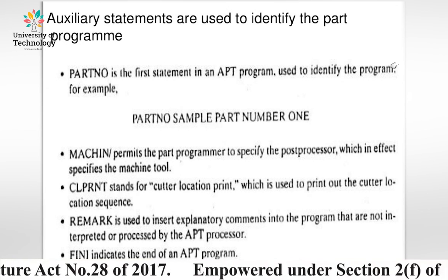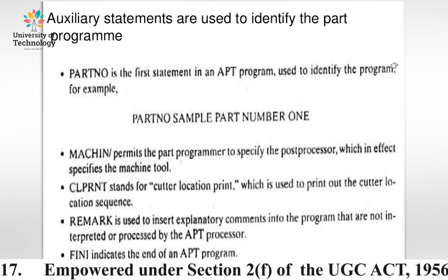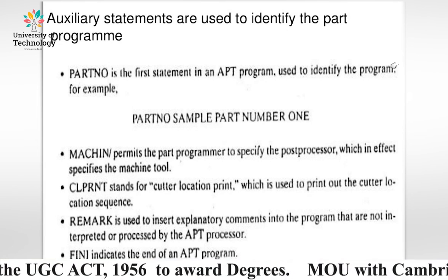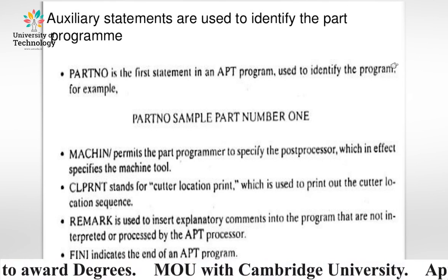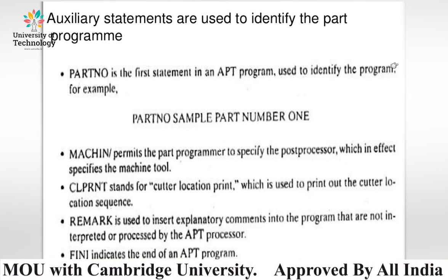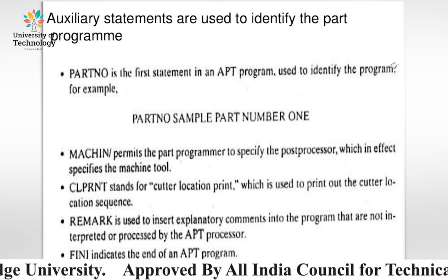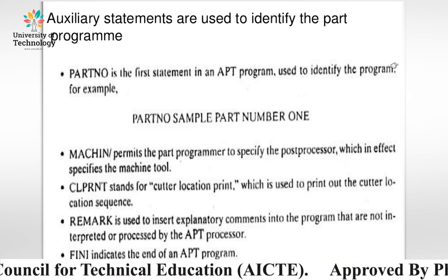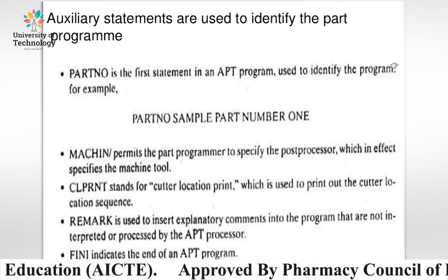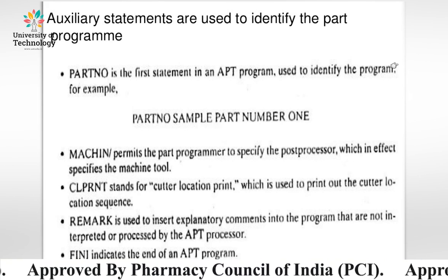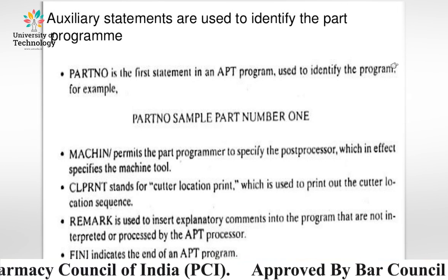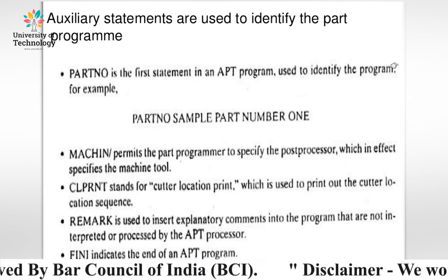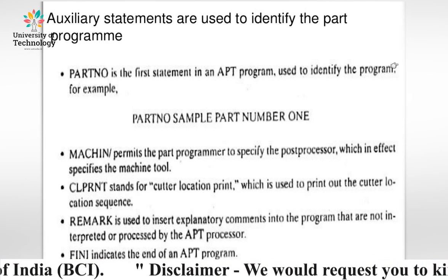If we have any remark, then use REMARK. Writing REMARK is used to insert explanatory comments in the program that are not interpreted or processed by the APT processor. And FINI goes at the end of the program. Writing FINI indicates the end of an APT program. Students, these are the basic statements of the APT language. Thank you.